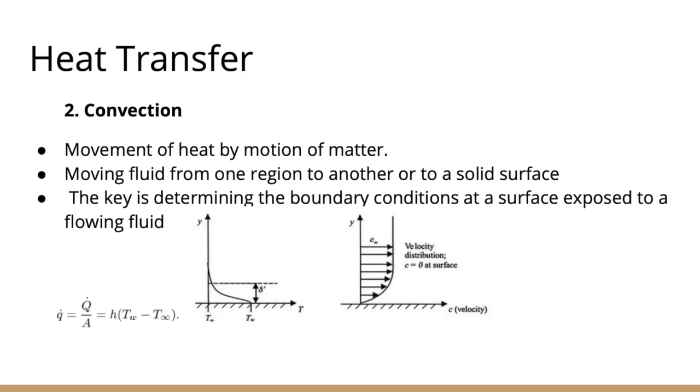Convective heat transfer can be forced or natural. Our model accounts for only free convective heat, neglecting the other one, for simplicity. It is implemented in our model, and it calculates the heat transfer by multiplying the specific convective heat transfer coefficient of the medium by the temperature difference between the surface and the bulk fluid.